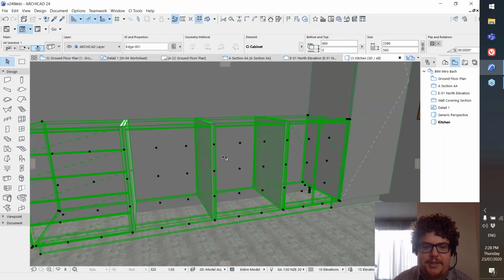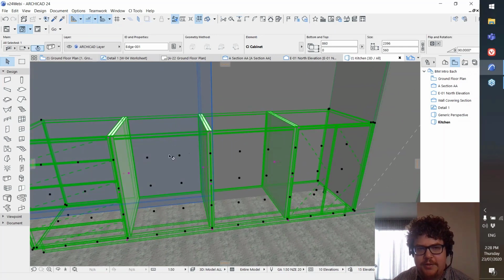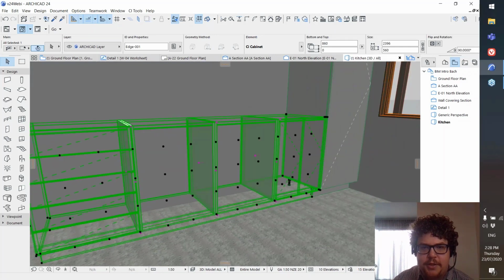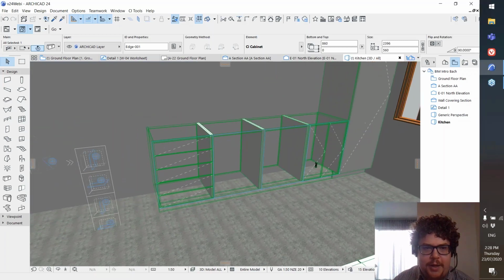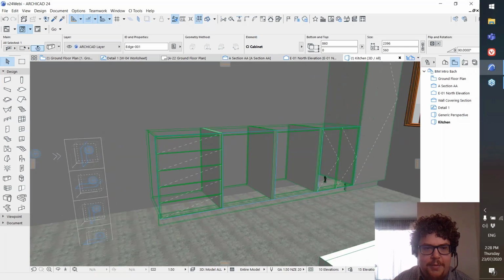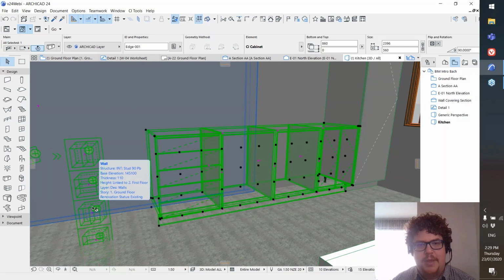So we're now in partition editing mode, and when we're in that edit mode, it changes the display of the cabinet to this sort of wireframe display so that you can see how you're setting things out while you're working with it. I'm going to zoom out a bit so that we can see the palette, but there it is. Unfortunately, the bottom of it's going through the floor there, but you can see the main edit modes here. So we've got vertical and horizontal dividers of various kinds. You can see this one here goes all the way to the back, whereas this one stops at the actual back piece of the carcass.